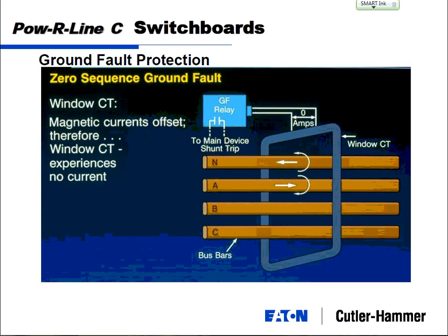So let me give you a better look at that. In the back of my switchboard, I've got A, B, and C, and neutral. And what current flows on neutral? Anything unbalanced. If you've got all three-phase loads, you shouldn't see any current on neutral. Normal buildings like this have almost all single-phase loads. Anything unbalanced, where you plug it in coming more off A and less off C, is going to flow into neutral. So you always need to monitor the current in the neutral as well as your A, B, and C.